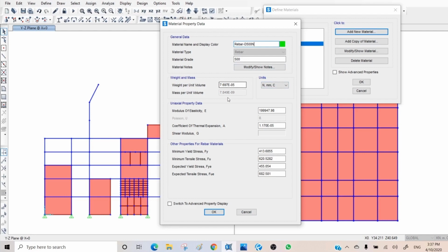Again, I can check the specific unit volume and everything here, and I can put the numbers here. So for rebar, the modulus is generally a little bit lower than steel, so it's 2E5, and the coefficient is a little bit higher, generally 1.2. Some of them really don't affect your design, so you really need to see how precise you need to be in adding the details. So here is 500 for rebar, and ultimate is a little bit more than 500, about 8%, so it's 540. And again, it's up to me. I will keep them the same, 500 and 540.